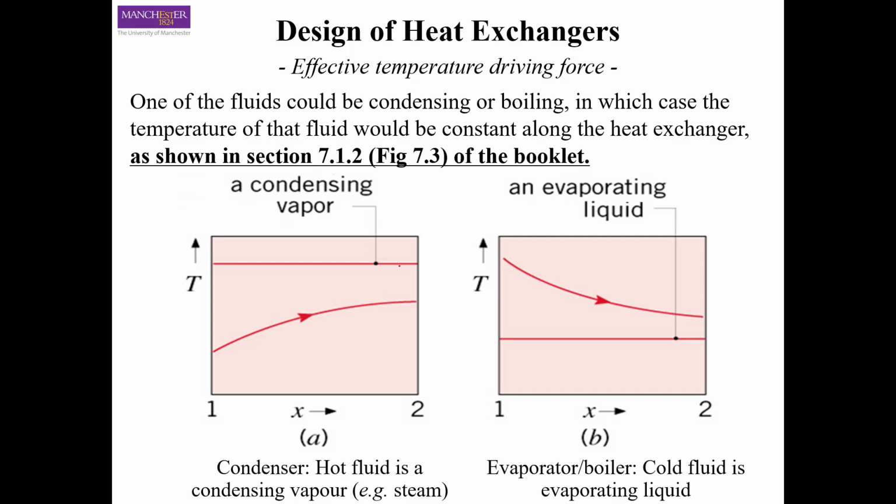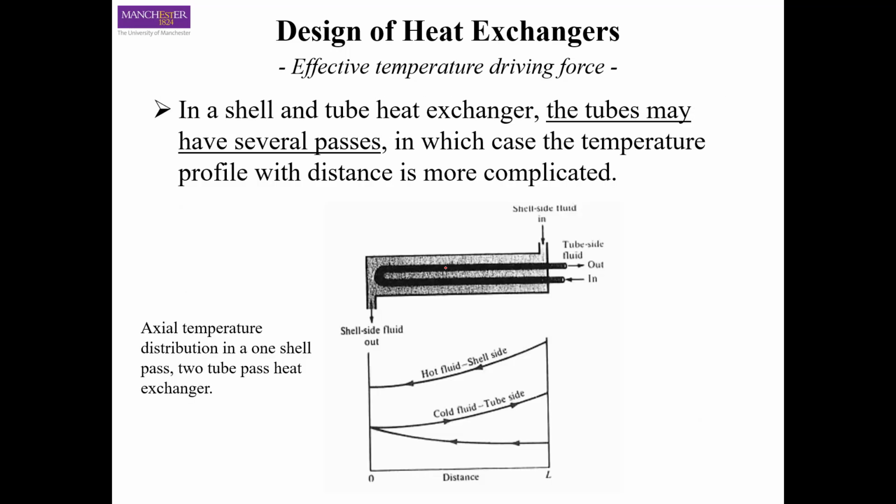So what we discussed so far is one of the easiest cases, where you have pure countercurrent or co-current flows. It means that you have a shell and tube heat exchanger with only one shell and one tube. Okay, so that is the simplest case of a shell and tube heat exchanger. We defined the temperature profiles in the previous slide, but in reality, you can have much more complicated situations, because this one shell and one tube heat exchanger is not going to serve you in actual life, because the heat exchanger duty available through it is too low. So you have to adopt more complicated configurations.